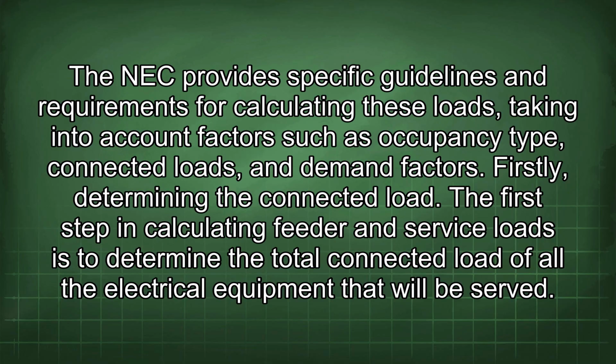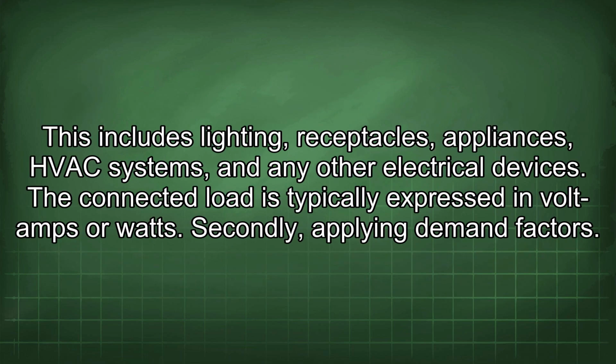The first step in calculating feeder and service loads is to determine the total connected load of all the electrical equipment that will be served. This includes lighting, receptacles, appliances, HVAC systems, and any other electrical devices. The connected load is typically expressed in volt-amps or watts.